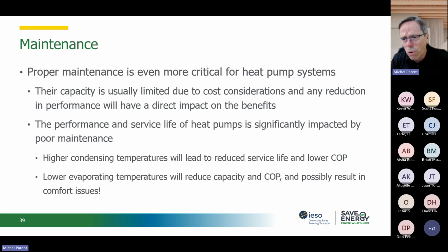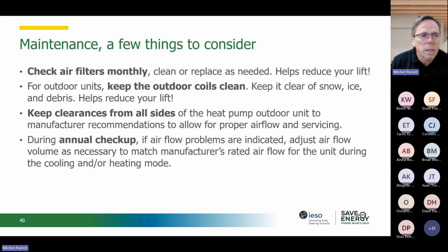Last word before we go to the Q&A is about maintenance. I told you maintenance is critical for heat pumps because your efficiency is really proportional to that delta, the pressure differential between the condenser and the evaporator. So you want to make sure it is maintained properly. You need to check your refrigerant level. You need to make sure that it is at the proper level, that your coils are correct. I'm not reading the slide, you'll have those slides.